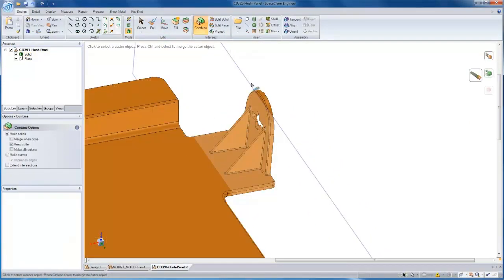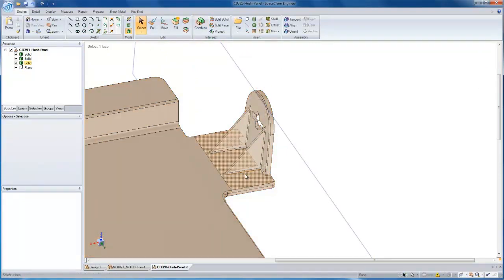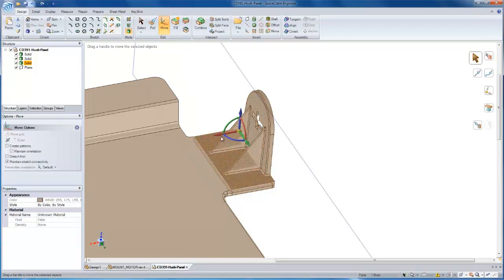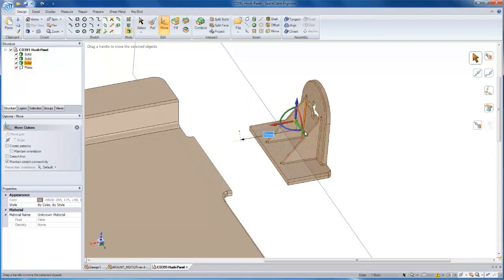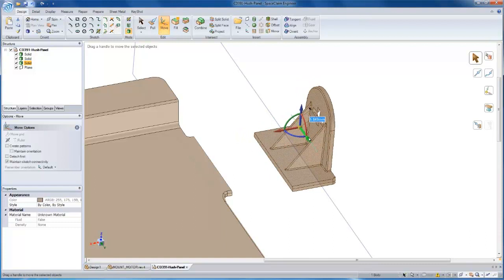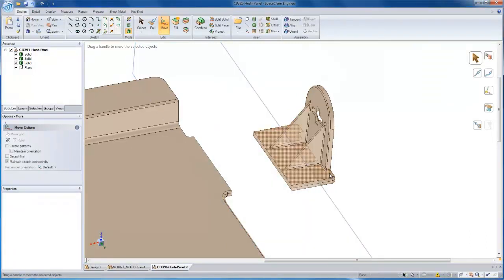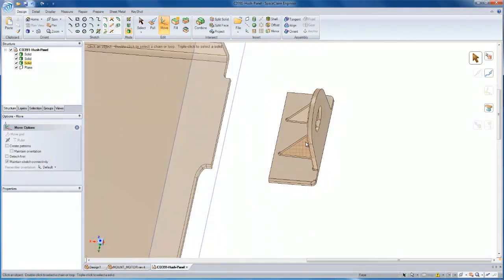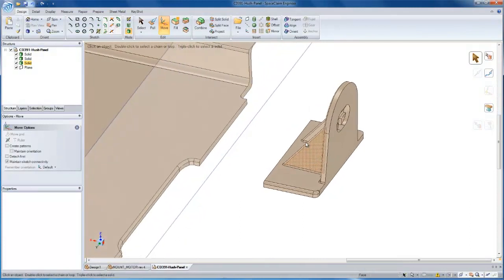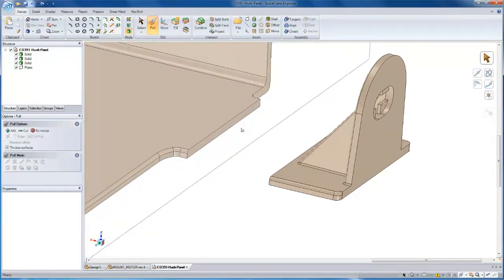What I'm doing is I inserted a plane, an arbitrary plane, into the model, and I'll use that to cut up the body. Now that it's cut up, I could take that section and move it as far away as I want. We'll say 30 millimeters, and let's go in the green direction as well. So I'm pretty much moving it around in that red-green plane. So maybe that's where I want that small boss and that the support ribs to be, and I need a new section of material to join those two back together.